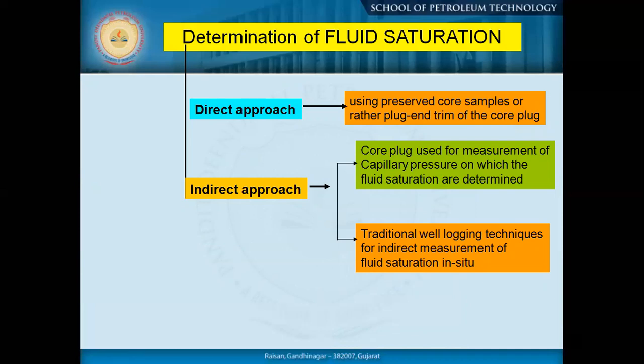Sir, collected during drilling time and preserved for in situ pressure and temperature conditions. Yes. The core barrel we use is actually auto-sealing, meaning once it collects the whole core plug sample, it can seal it. So pressure and temperature can stay in the original condition. That's why this core is called a preserved core. Once we get a preserved core and take it out, from that we can get certain information about the original fluid saturation.